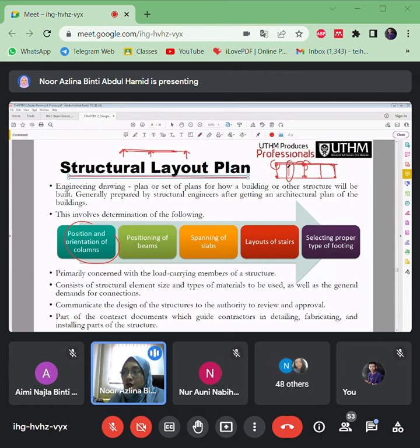That means the load of this beam will transfer to this main beam. There are 2 secondary beams here, so there will be a point load from the first secondary beam and another point load from the second. This is how you idealize the load and the support for the estimation of the loading.